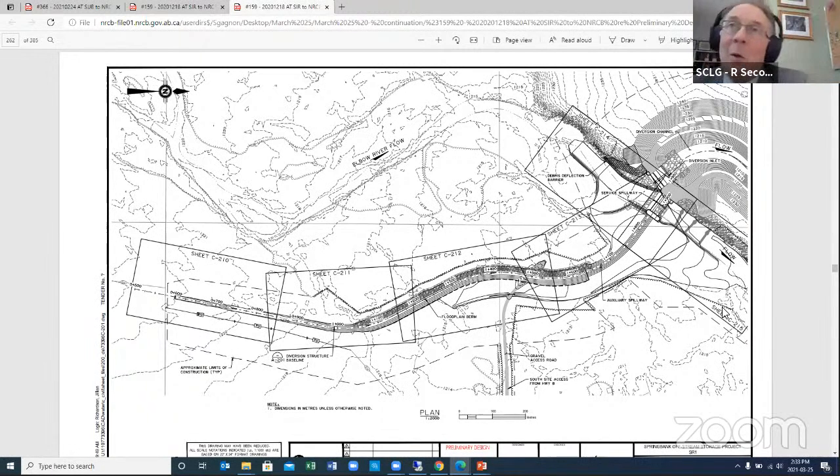So before you mentioned there were a lot of spillways. So what is the function of the auxiliary spillway? As I said, it adds capacity in the river to pass additional flow downstream. So when water gets above 1216.5, more flow will go down that way. And that in turn makes sure that our water surface elevations upstream of that structure are low, and so it reduces the amount of flow that goes then into the channel.